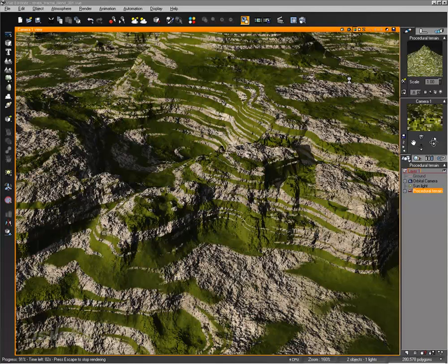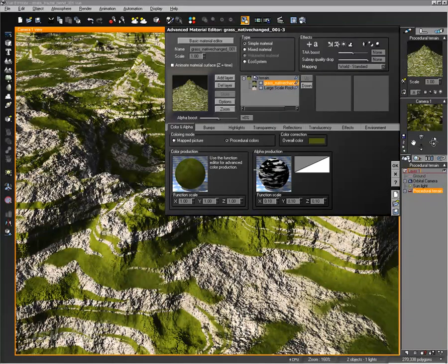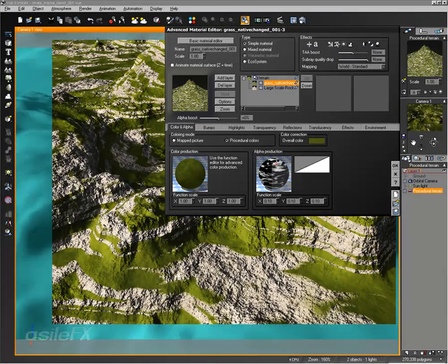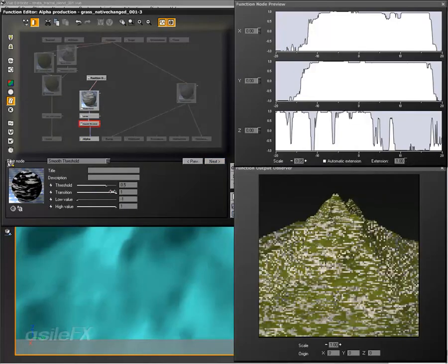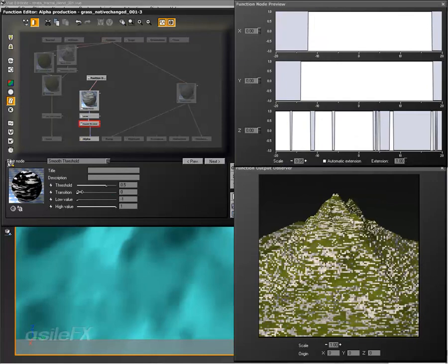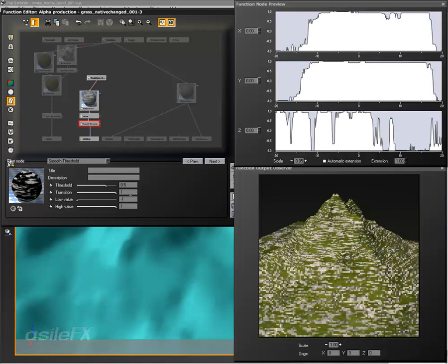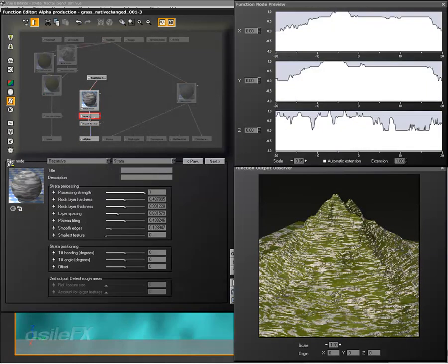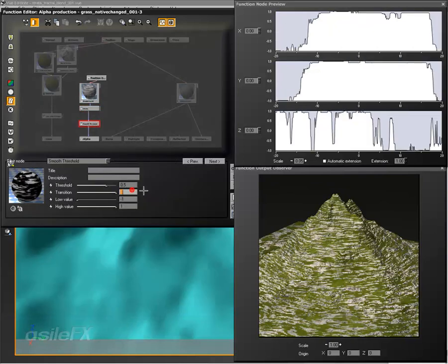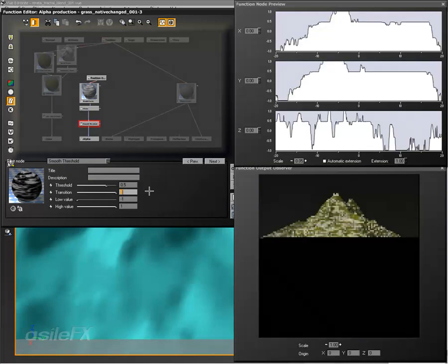So the only thing I'd really want to do to improve this, because of course it doesn't look all that great, is going back into the smooth threshold and just increasing the transition. If I decrease, it's going to make the cutoff even worse. But because the gain output is so high from our other fractal, I do want to increase transition a little higher.